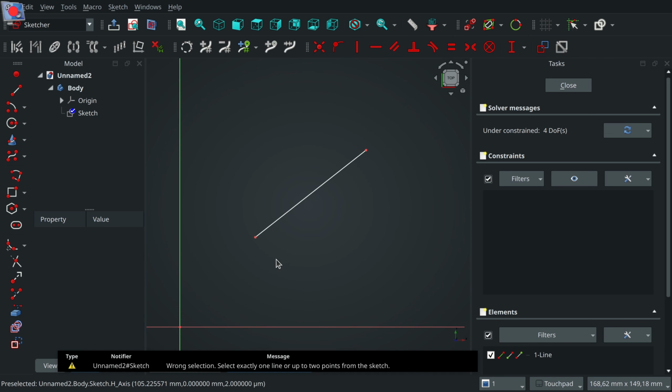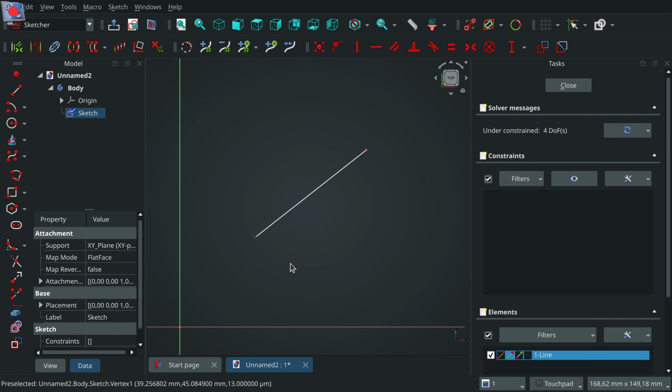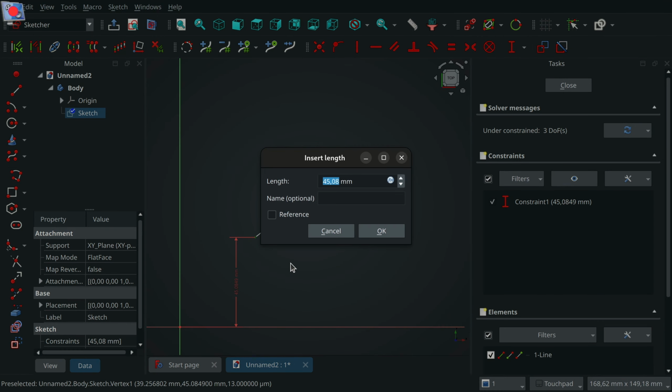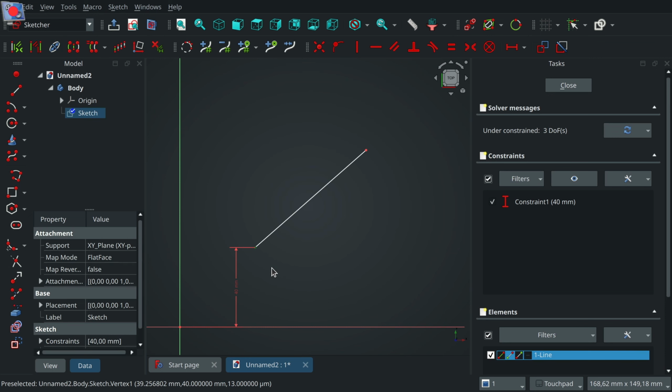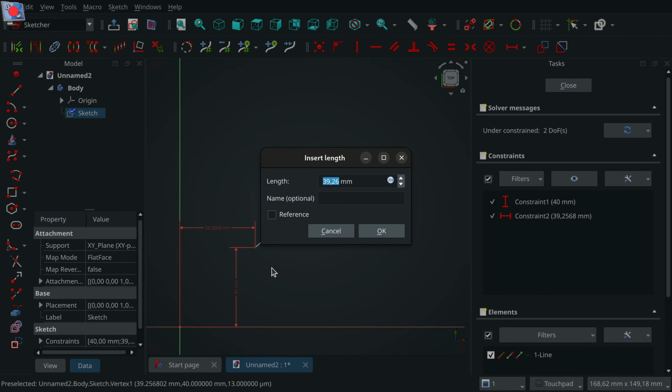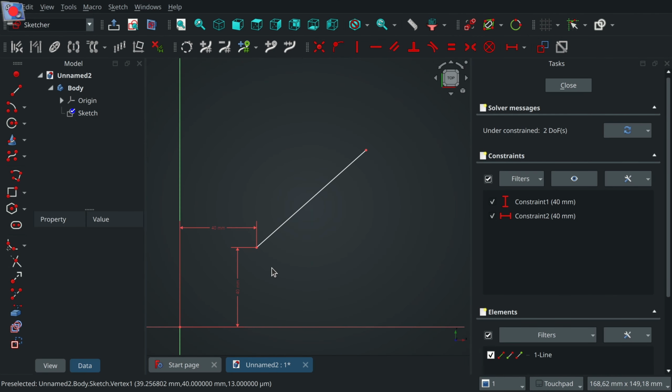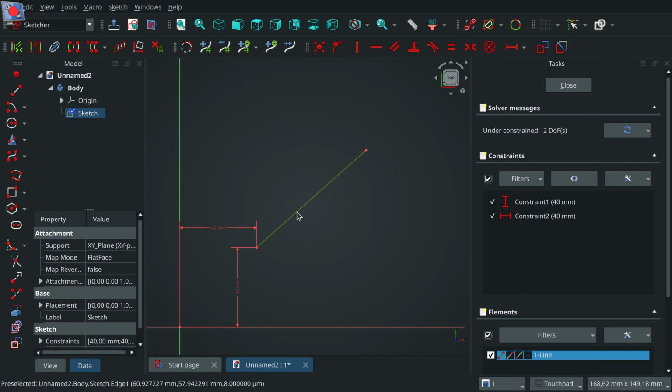In the latter case, with version 0.21, this means that you select a point, then you either press a shortcut or click a button in the toolbar, then you dial in the number, press enter, then you once again select the point, either press a shortcut or click a button in the toolbar, once again dial the number, enter, then select distance.